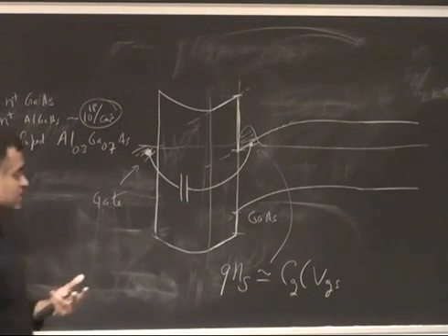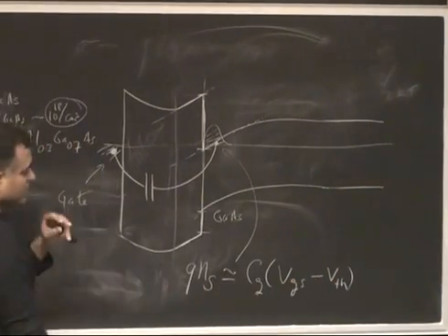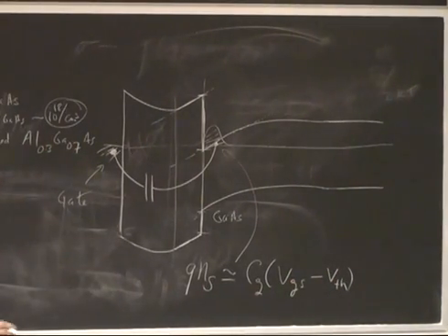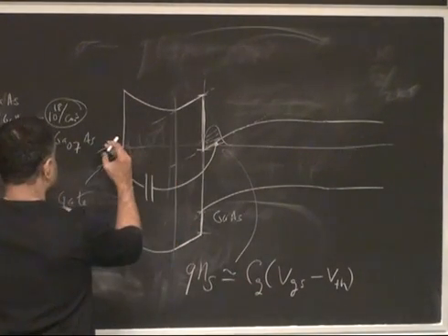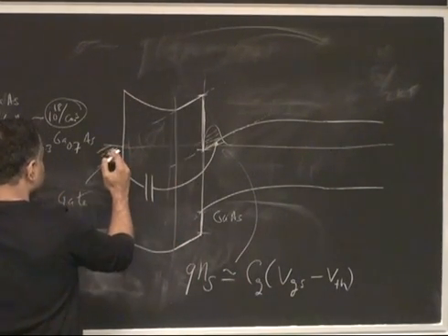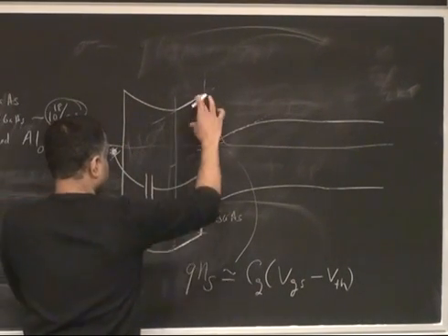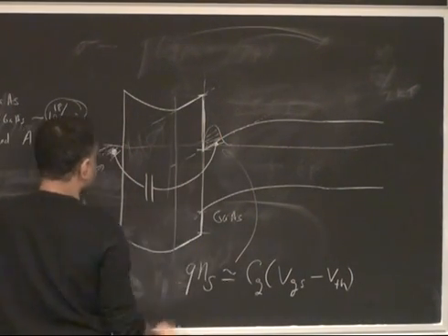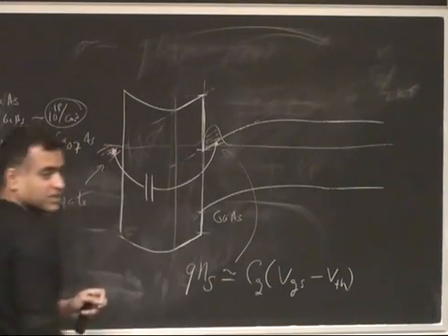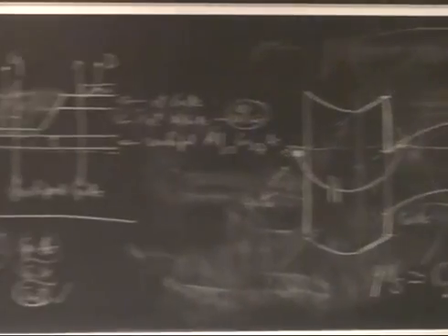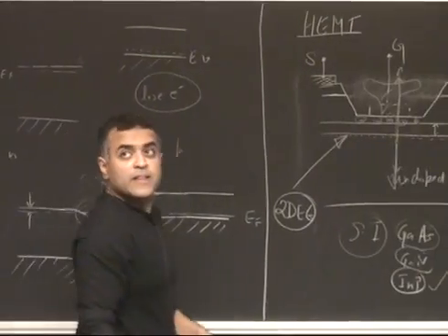Okay? But here we will see that there will be a threshold voltage. This is rough order. So as I increase, for example, the gate voltage, I can increase the carrier density. If I make it more positive, if the gate voltage is more positive, I pull this down. It gets deeper. You get more electrons here. What's going on is actually you're moving electrons out from the metal, putting them into the 2D electron gas. So that's okay. So all right.